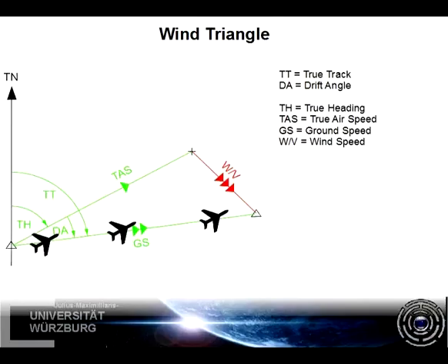In the post-flight scenario, the path flown over ground is called the true track, and the angle between the true airspeed and the actual flown true track is the drift angle. It equals the wind correction angle if the wind was assumed correctly. Otherwise, the difference between wind correction angle and drift angle is the drift additional.